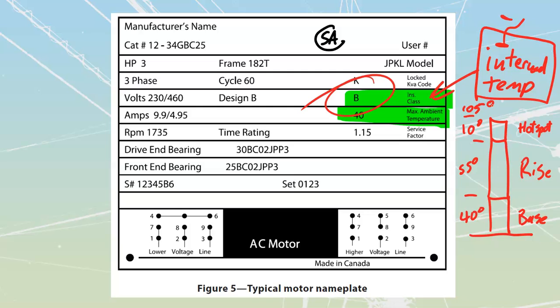And then my H, which is going to be the strongest one over here, is going to get a greater rise. Now, because each of these is going to have different values of temperatures, it is still going to affect the connection that I'm going to have. 4006, which we talked about this year, talks about temperature terminal ratings and the fact that our loads are not allowed to overheat our wires.